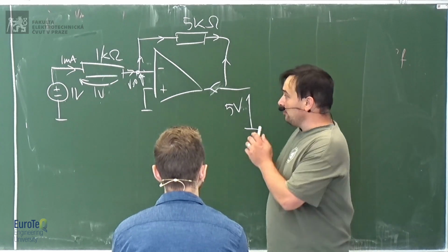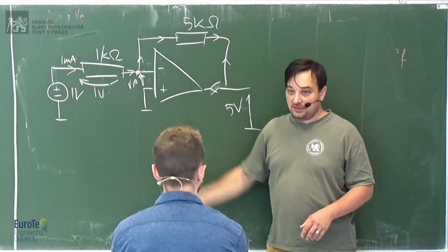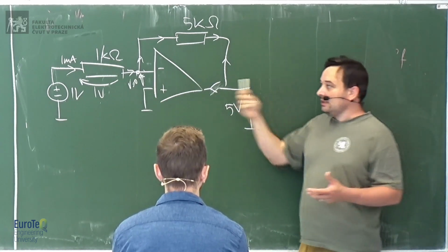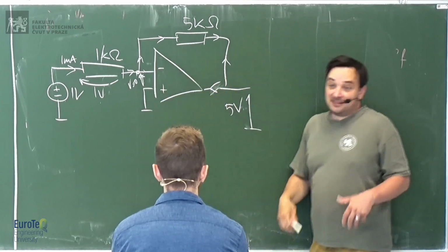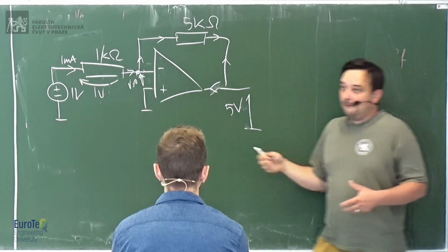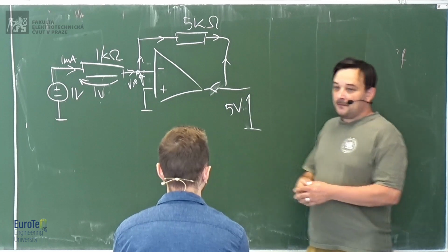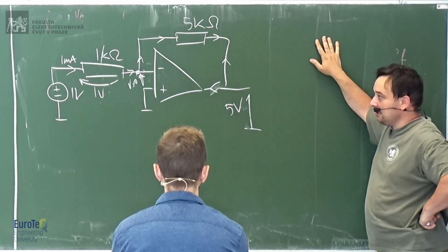This is important because, again, people think that this is a short circuit. It's not. It's a virtual short circuit in a sense, because there is no connection between these 2 points. It's imposed by the rules of the circuit, okay? But it's not actually connected. It's not actually a short circuit, okay?